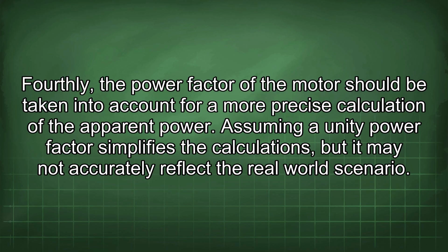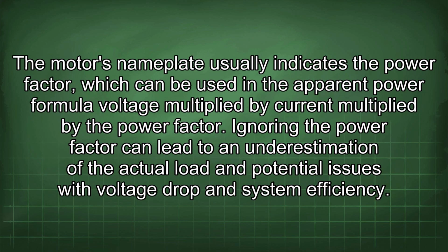Fourthly, the power factor of the motor should be taken into account for a more precise calculation of the apparent power. Assuming a unity power factor simplifies the calculations, but it may not accurately reflect the real-world scenario. The motor's nameplate usually indicates the power factor, which can be used in the apparent power formula: voltage multiplied by current multiplied by the power factor. Ignoring the power factor can lead to an underestimation of the actual load and potential issues with voltage drop and